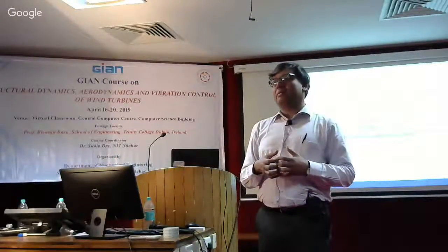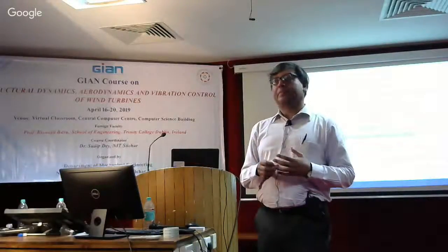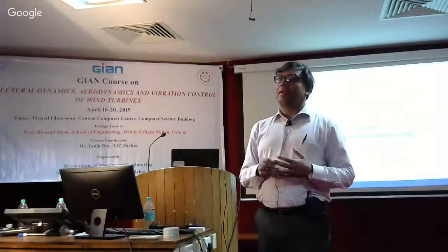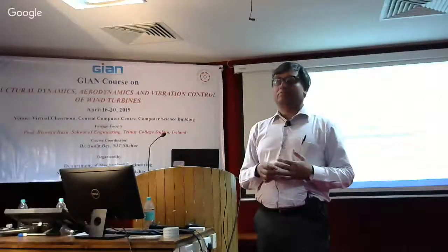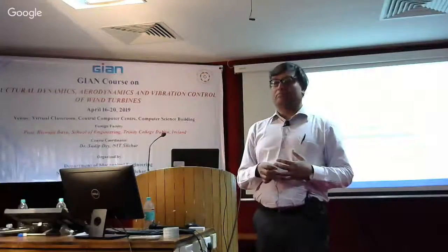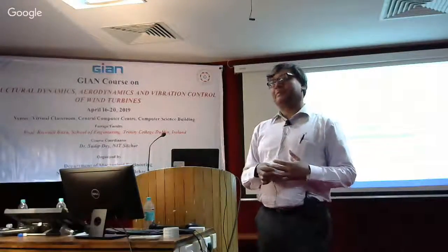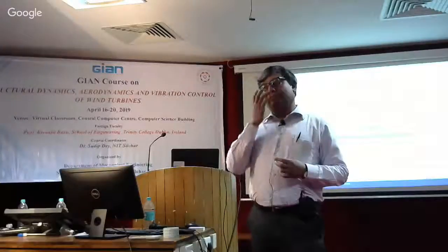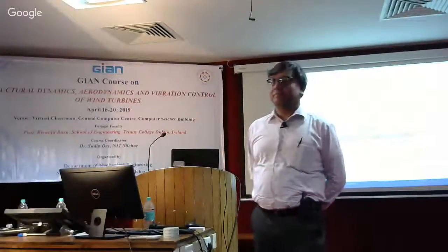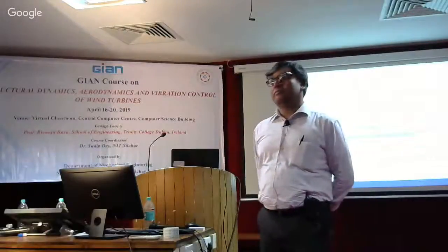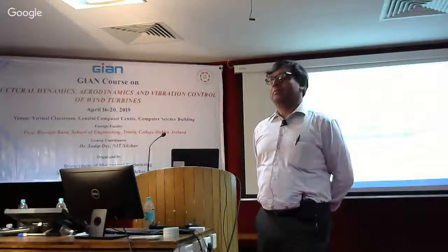Do you want to decouple it? Because when MIMO system comes, some of the interactions would make it difficult. Yeah. So usually in MIMO systems, we try to decouple it and make it into SISO systems, to make the controllers easier. So if and only if each blade's controls are influencing each other, then only we have to think of decoupling. And only if the interaction is negative. If it is positive, then we don't have to think about decoupling.